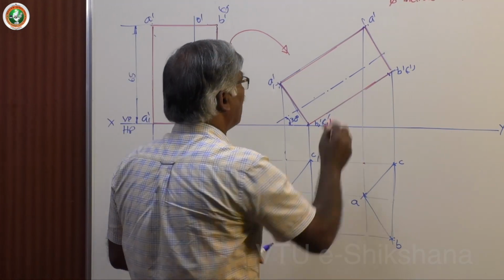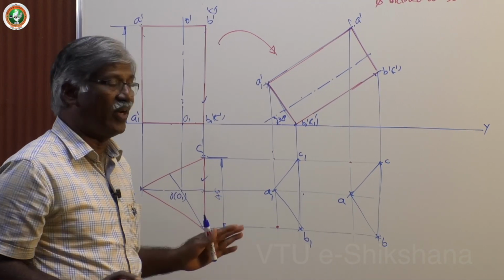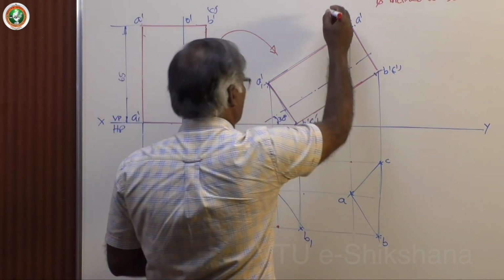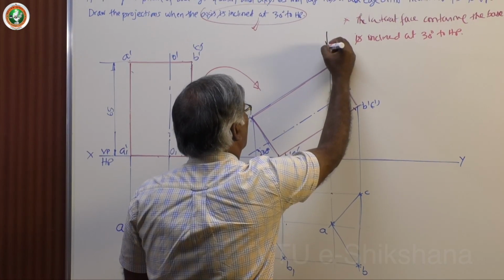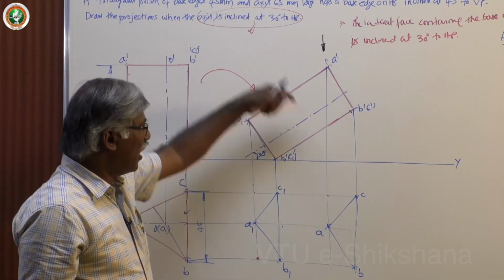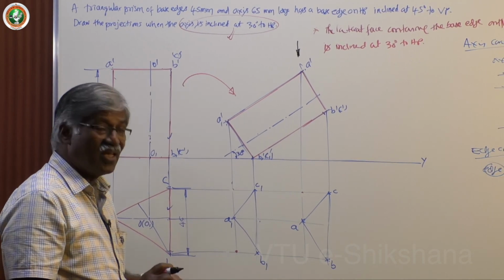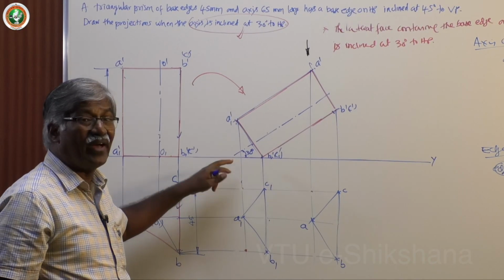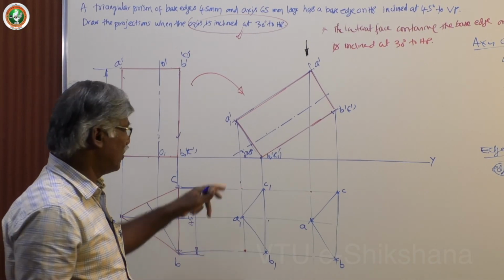Now, method 1. How to complete the given top view, front view, whether it is the final front view or the second top view. Assume that I am here. The observer is here. I am going to complete the top view. The first and foremost thing is you have to identify the farthest item from you, whether it's a corner or an edge.